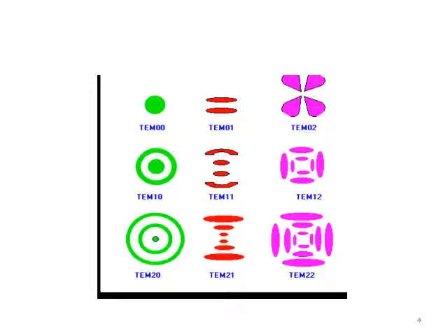Clearly, the mode pattern affects the distribution of output beam energy, which will thus affect the machining process. The diameter of the laser beam is usually defined as the distance where the intensity falls to 1/e² of the total power. The higher the order of the mode, the more difficult it is to focus the beam to a fine spot, since the beam of higher order is not from a virtual point but a pattern, as in this table below.